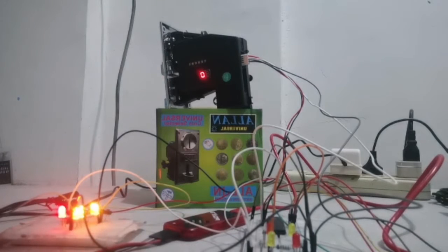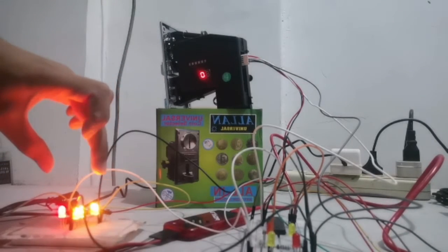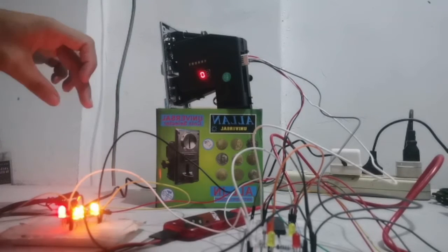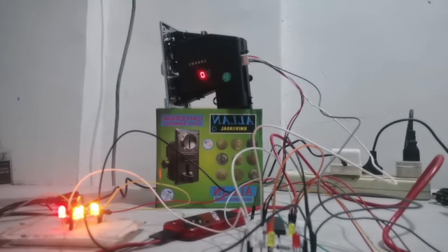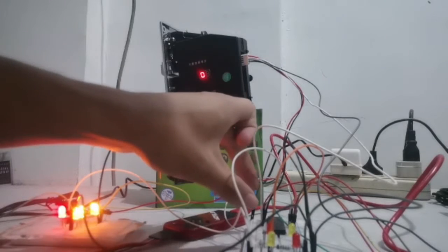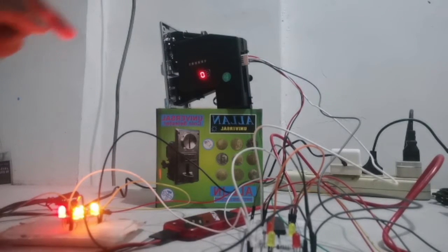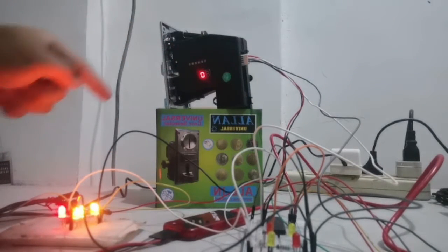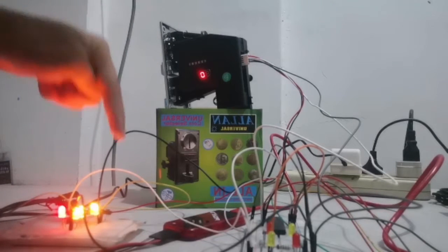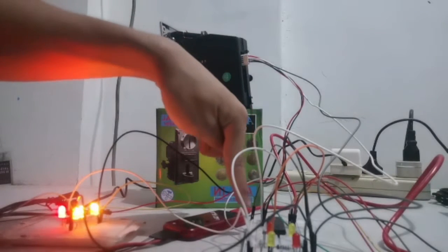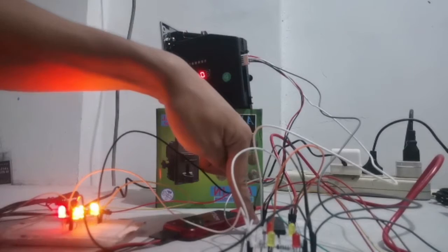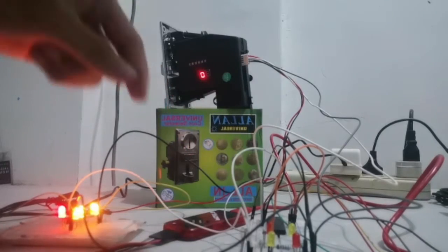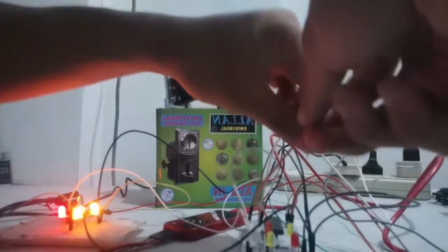So I have a voltage divider network here that has the 12 volts for here, 5 volts for our circuit here, and I've also connected our coin slot through our power supply and our RB4 here, which is the input. However, I will connect the LED to the port RB0.